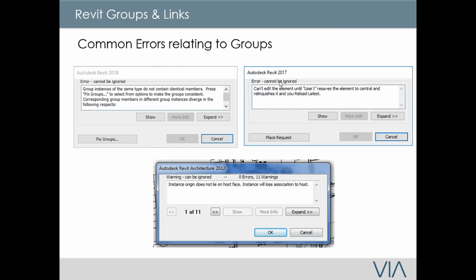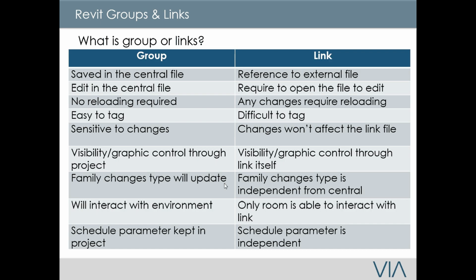The other error you could encounter is if the group is hosted on a face. When you start mirroring, it tells you that it loses its association to the host. Sometimes it will break your group. It's something that can happen, so just be aware of that.